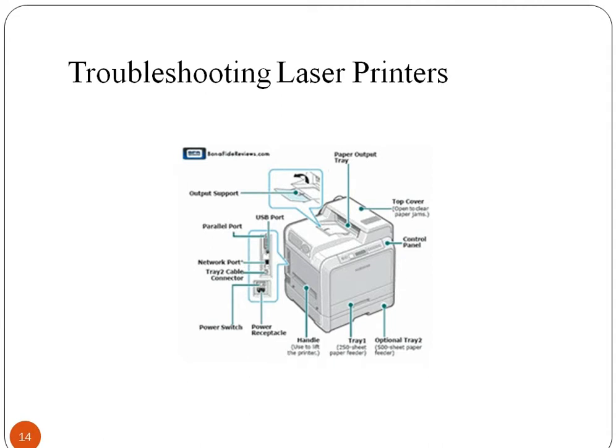Loose or smeared toner. Here is an easy one. If the toner is loose, the fuser is not melting the toner and thus the toner is not fusing with the paper. Make sure the fuser is heating. If not, replace it.